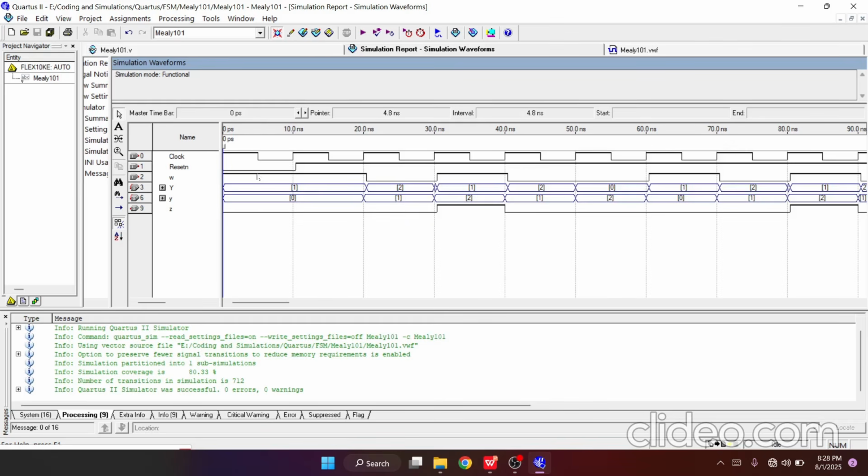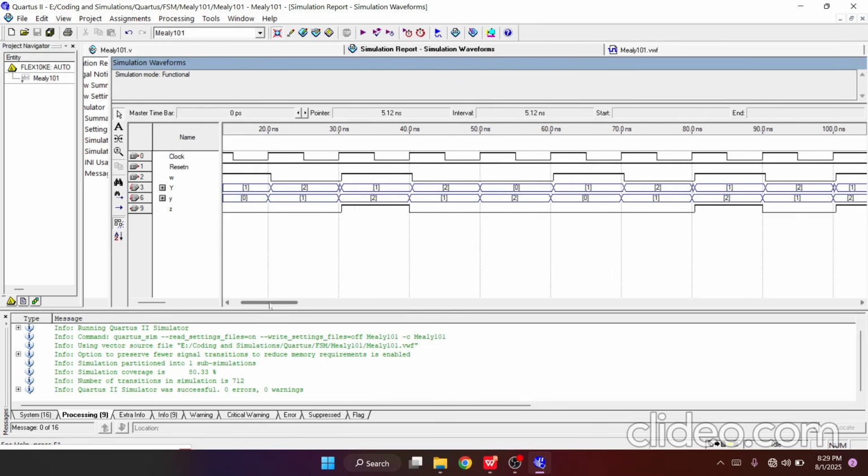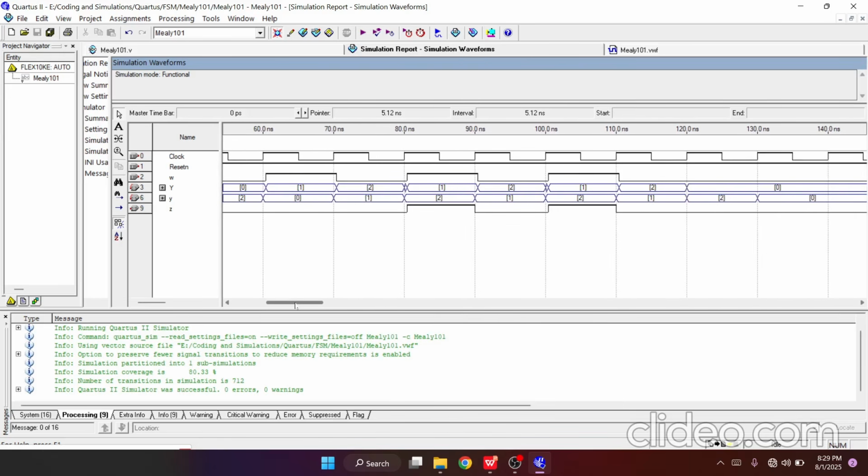All right, let's see if we are getting correct value or not. So for the first clock cycle, I am keeping this reset n equals 0. So basically this particular W equal 1 value will be discarded or ignored. After this 1 is counted, we are getting first clock edge, so this 1, then 0, then 1, and when we are getting this one, the output is getting high in the same clock cycle, which tells us that this is a Mealy type circuit.